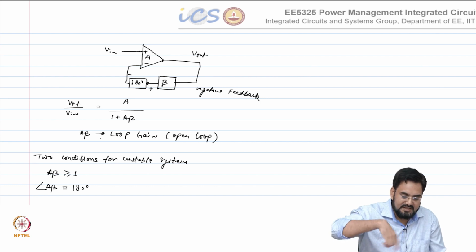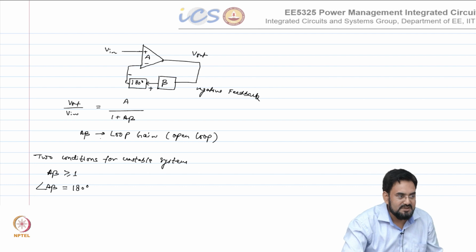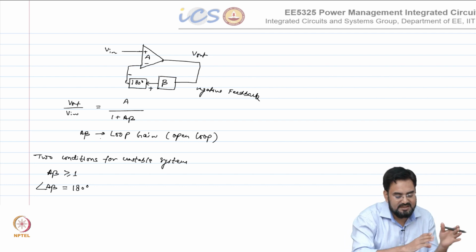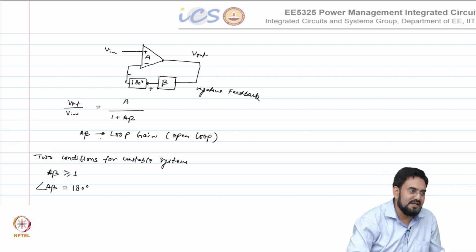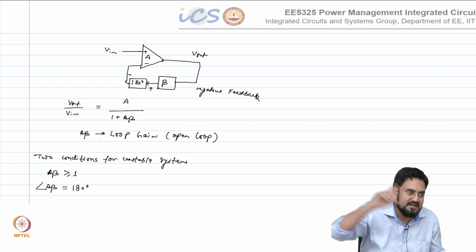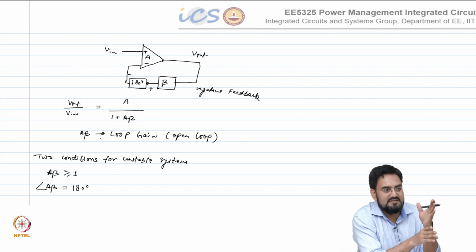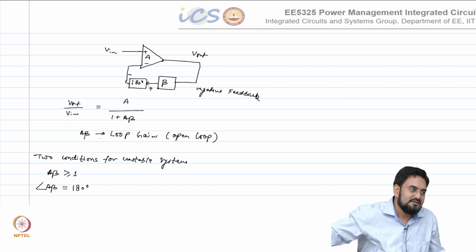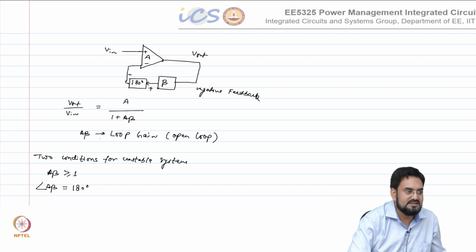If you convert it into a sampled system, then it will become a clocked system. Here we are looking at continuous, but in order to understand, you can think of it as a clocked system. So every clock cycle you are sampling the output, feeding it back, sampling, feeding it back. But if you are multiplying that by a gain which is less than 1, then it will decay and never build up, so it will not be unstable in that case.